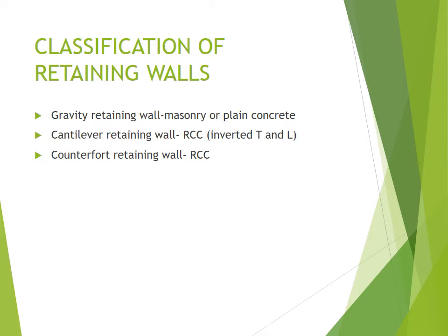Next we look at the cantilever retaining walls. In cantilever retaining walls, we normally have the toe, the stem, and also it is normally reinforced. So it consists of cantilever beams, vertical stem, toe, and heel projection. In some cases, the toe projection may be missing.